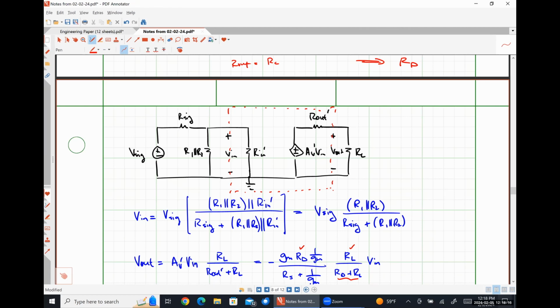Because this doesn't have to be hard. If we can understand how the basic little parts work, we can just use an easy to manipulate equivalent circuit and then connect the rest of it to that equivalent circuit and just figure out what's happening, okay? So we're going to spend, once again, the majority of our time on how the BJTs work, because the only difference between the MOSFET and the BJT from a small signal perspective is that the input resistance, or R pi, is infinitely large. Everything else works out exactly the same.